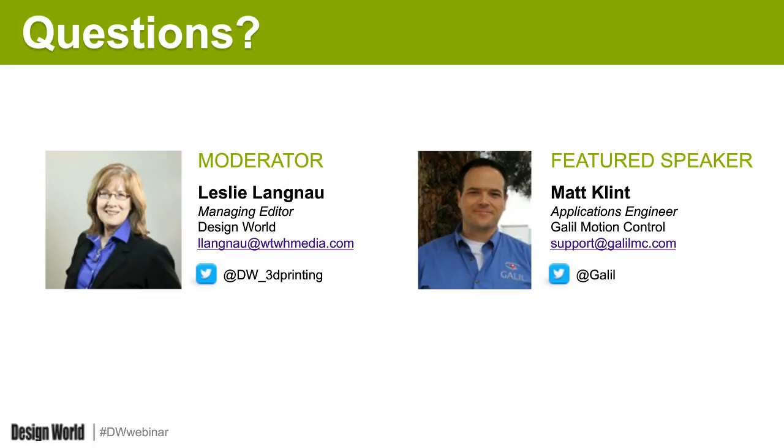And now you've got packets bouncing every which way, back to the master, back to every other slave on the drive. Long story short, standard Ethernet hardware like routers, switches, and hubs, wired or wireless, are not compatible with EtherCAT. Ethernet communication, absolutely, is going to be compatible with it. That's what they're for, with the caveat that in motion control, wireless is still an emerging technology.